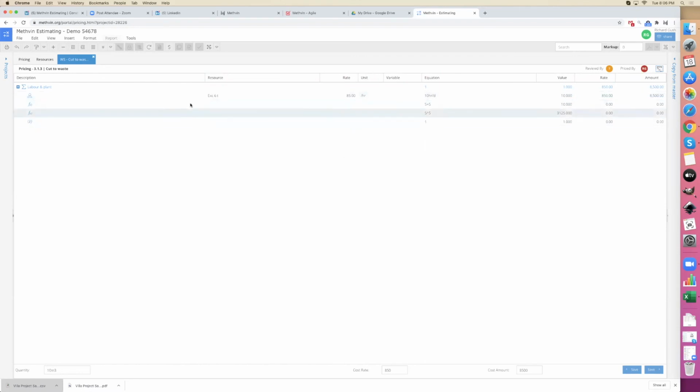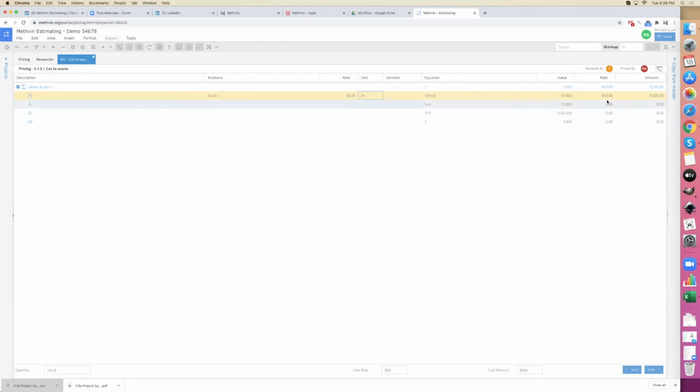And let's say this is a small subdivision, and as I said before, it's the true cost. We've got the cost of $850 divided by the productivity. The productivity this excavator will do in a small subdivision would be, let's say, 85. So I'm dividing it by the productivity, meters cubed per day. So now to excavate that material from cut to waste, it's going to cost us $10.